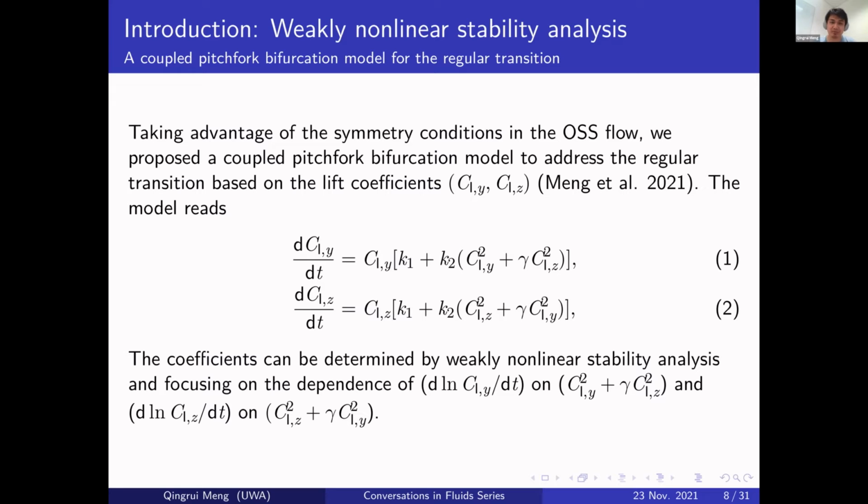Because it is a three-dimensional problem, we of course have three hydrodynamic coefficients, and we assume the two lift coefficients, CLY in the y direction and CLZ in the z direction, are good enough to model this problem. Taking the symmetry conditions, we can write a unique Taylor series expansion, omit the higher orders, and arrive at this form.